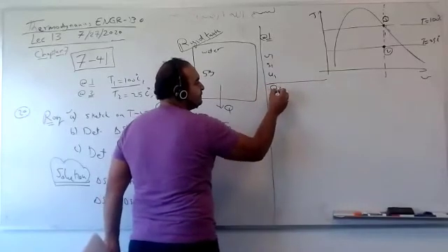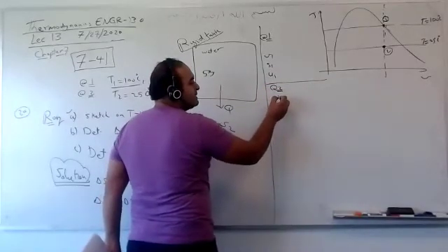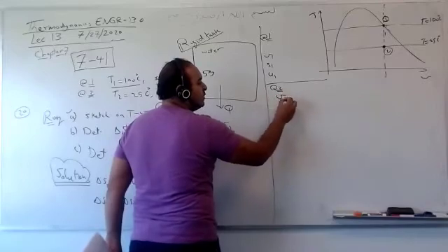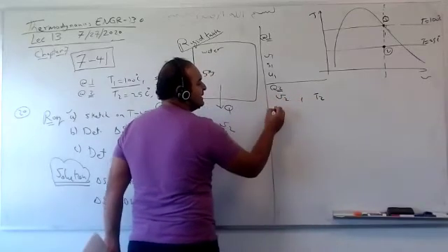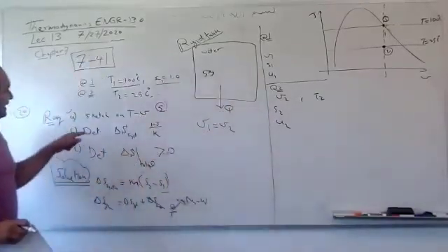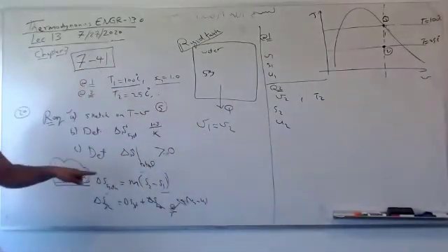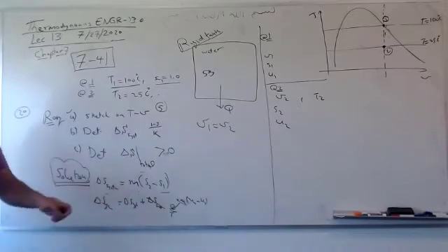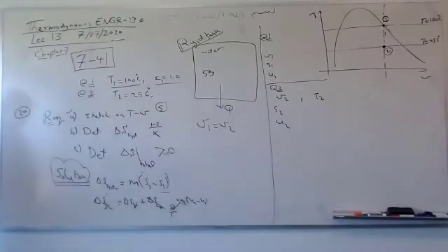At state 2, I will start with V2 and T2 to obtain S2 and U2. S2 and S1 for the second required. U1 and U2 for the last required, because I need Q. How much heat removed from my system, added to the ambient. Okay, guys, does it make sense for you?